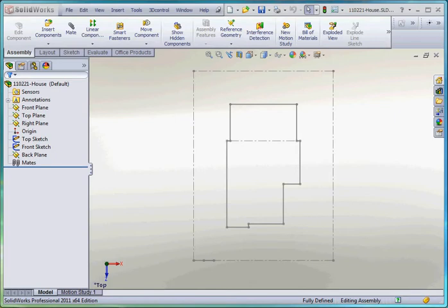Just to review what we talked about in our first videos, we have essentially two sketches that are designed to drive the whole design, and those sketches exist in both the top and the front sketch. The top sketch is the primary sketch. It drives all the other sketches and the model associated with it from that point on. The top sketch defines the basic footprint of the house.